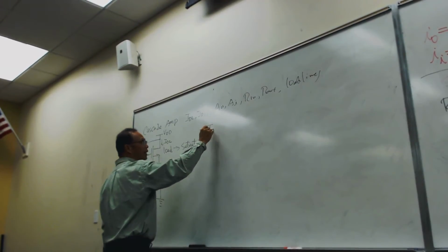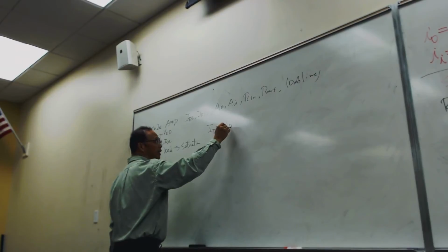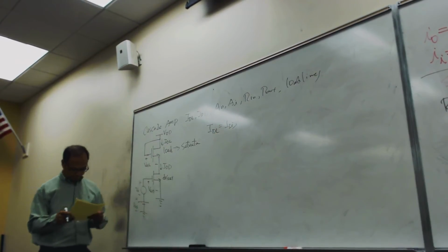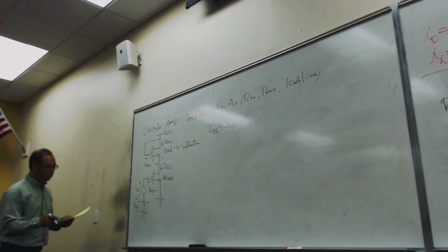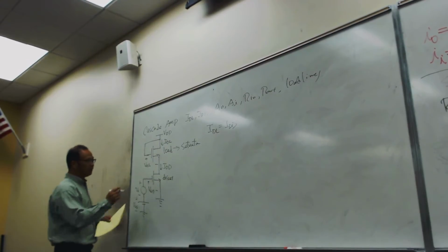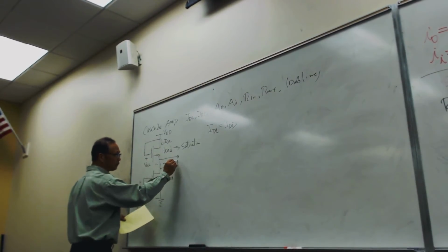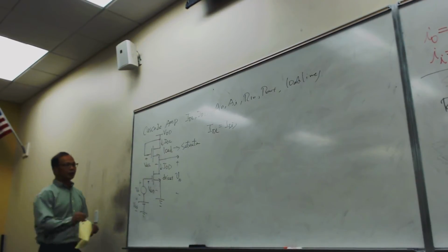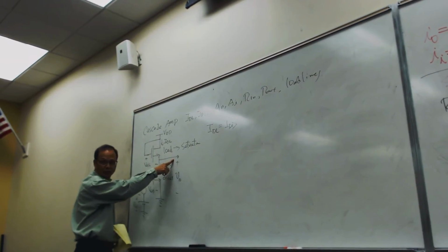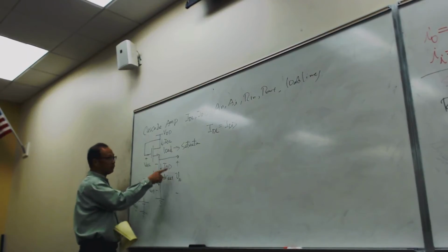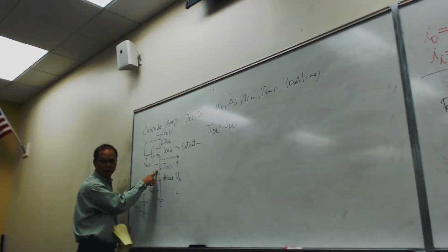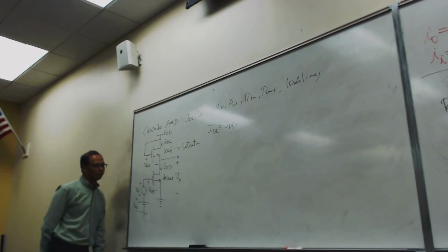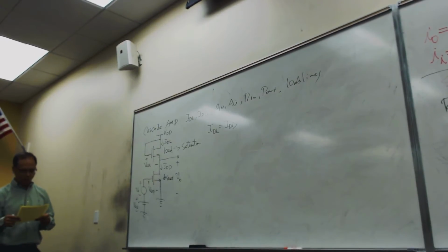First of all, you should know that IDL is the same as IDD, right? Oh, where's V sub O, huh? V sub O is taken from here. So that's V sub O. Because there's nothing connected to the terminal here, this is open, right? So the current here must be the same as the current here. Okay?